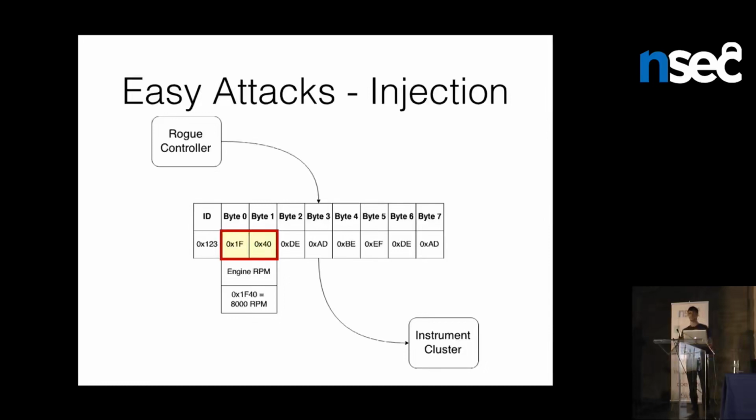If you send the messages at the same time, it's actually sort of strange. For every bit in the message, if there's a 0, the 0 always wins. So that's just how it works at an electrical level. So you can inject stuff, and if you have more zeros, then you're the winner.